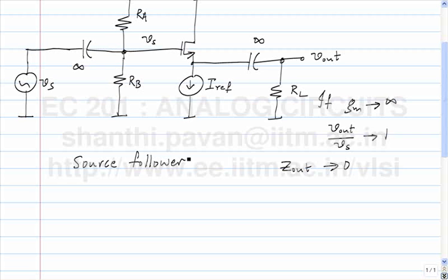The terminology is quite similar to that used when you build an op-amp based unity gain amplifier. The output follows the input, just like how the op-amp based unity gain amplifier is called the voltage follower. The incremental signal at the source follows the incremental signal at the gate. And we derived expressions for the gain, the input impedance and the output impedance when the GM is finite.